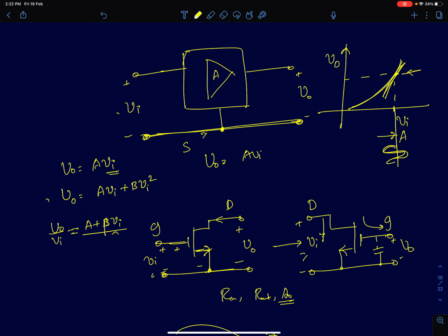So coming back to this discussion where I discussed an amplifier generally can be seen as a 3-terminal device, one as an input, one as an output, and third as the common terminal. So by this definition, if you see a MOS device has 3 terminals, I can then define 6 possible amplifier configurations in which I can use a MOS device as an amplifier.